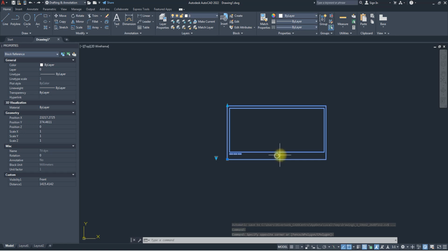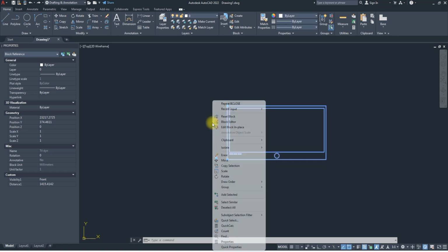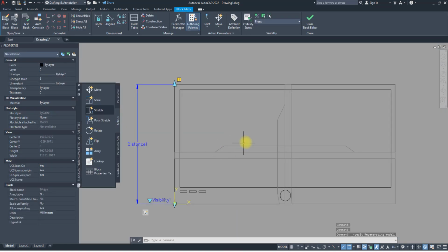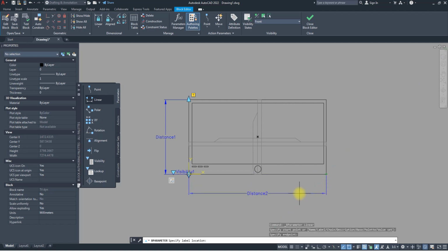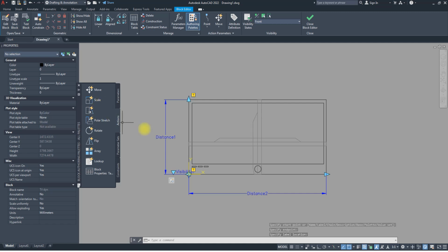What if we stretch this whole place? Because that back has to stretch. Yes, because I don't want to see this. Let's try it, we can always try. So let's add a parameter from here to here. Then go and add an action. You want to stretch. Select the parameter I want to stretch.